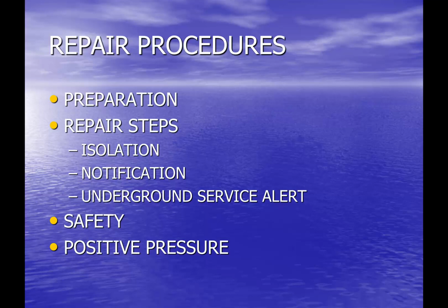The concept of positive pressure is to reduce the possibility of getting dirty water into the main. If water is coming out, it's not going in. It may reduce the potential for contamination, may reduce the overall need for disinfection, may reduce the possibility that you're draining water out of your customers' lines. But it introduces a significant set of challenges. So it's one that has to be weighed on a case-by-case basis during repairs.